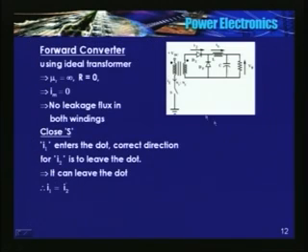See in this circuit, when this current becomes 0, this also will become 0. If this becomes 0, this may not be 0. Let me tell you one thing, this is inductor current. Output is a current source type, similar to buck or Cuk converter. I can represent this as a current source. This current may remain approximately constant. So when I close the switch, I2, that is equal to IL, increases.